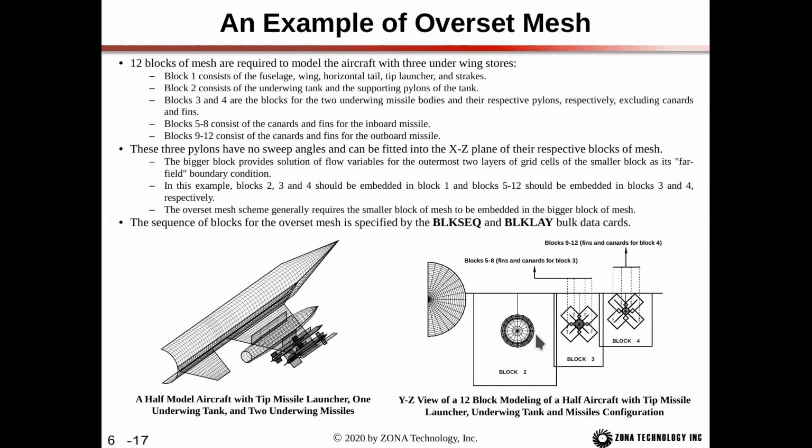All of the layer 2 blocks are allowed to hole cut the layer 1 block, and the layer 2 blocks are allowed to be hole cut by layer 3 blocks. And then furthermore, the layer 3 blocks will only communicate with the layer 2 blocks. The layer 3 blocks will not talk to each other.